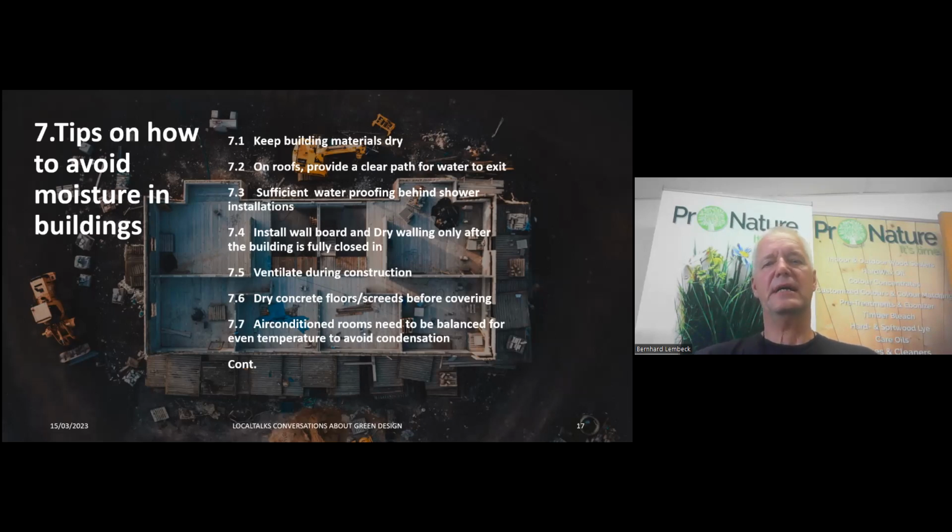Another important point, air-conditioned rooms need to be balanced for even temperature to avoid condensation. In some of the office complexes in Cape Town, which are sealed very properly to avoid the cool air going out again, there is often a problem that there is plenty of condensation on the inner walls and sometimes even on the outer walls.